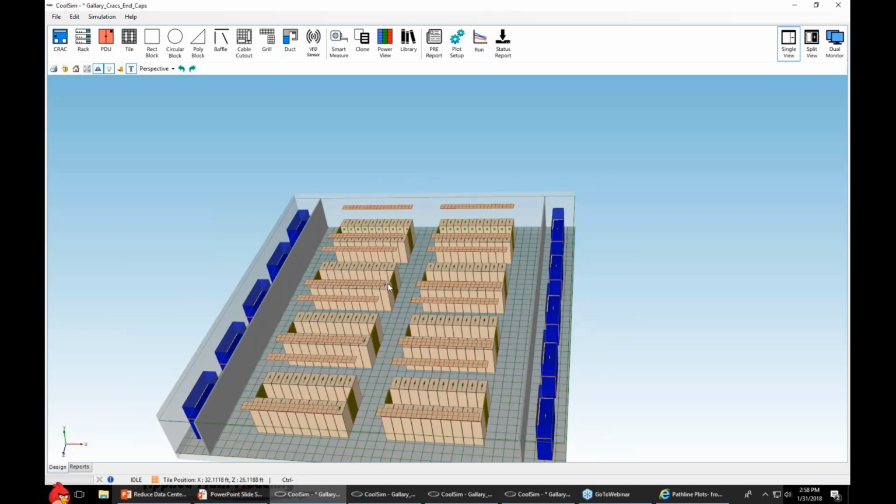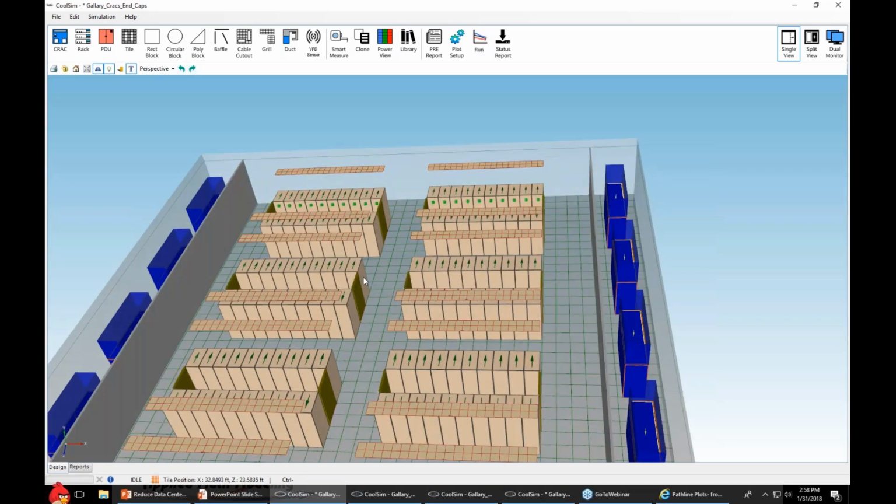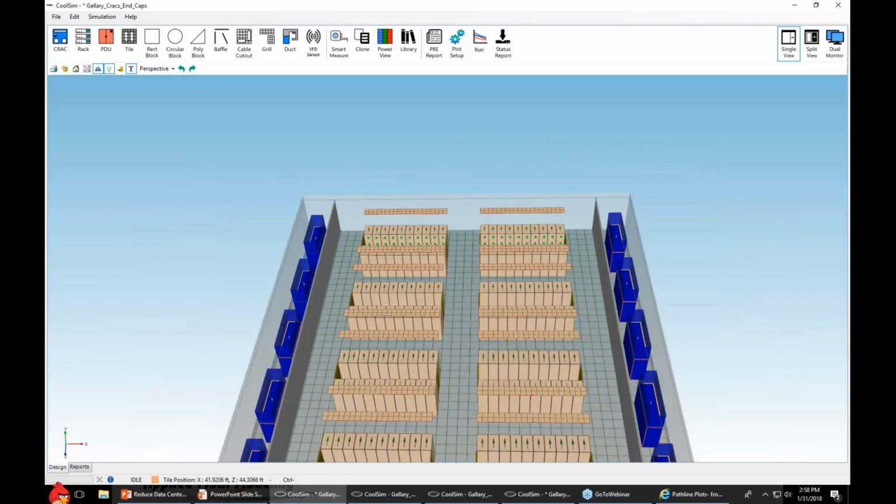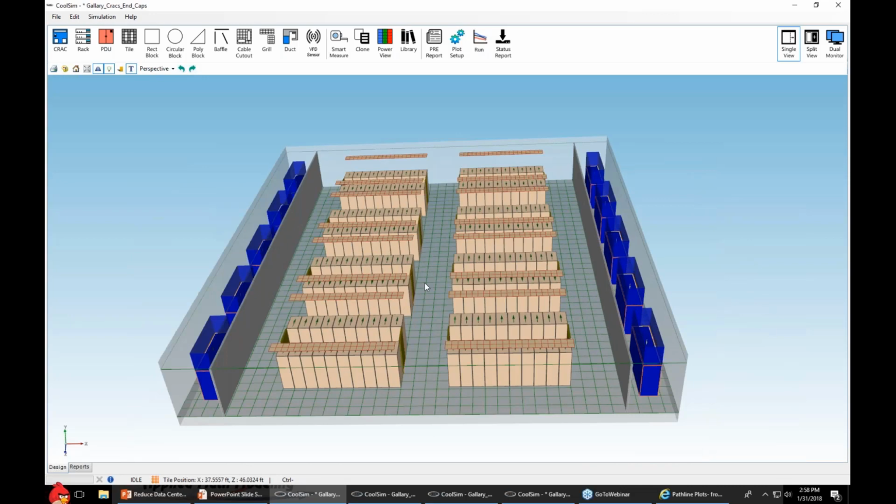And I like to drive VFDs off temperature and not pressure, but many of them are set up with pressure. The problem is the pressure is not uniform under a floor. It tends to vary as a function of location. It varies as a function of data center design. For example, if I had all these AHUs on one side, which I have seen, and none on the other side, then you'd have big pressure variations from left to right, and on the right you'd have tremendous pressure under the floor, and on the left you would not. It would build towards the wall.